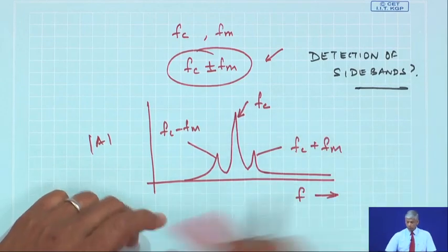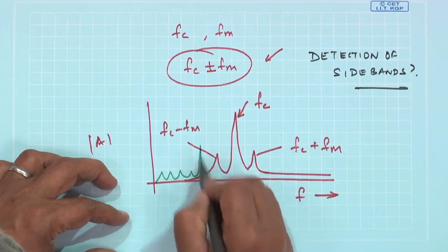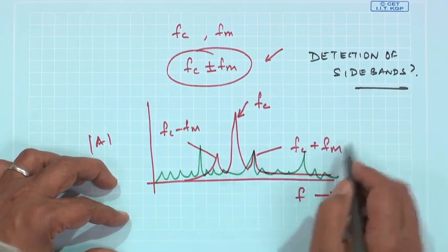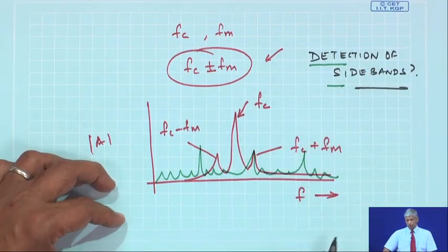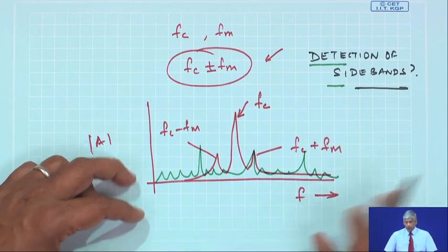Why? Because in a machinery signal where we are measuring from, say for example, a bearing location, there will be instances where there will be a lot of other frequencies in such signals. So, the detection becomes very difficult. So, this is another technique of detecting sidebands in a signal, and this is actually done through what is known as Cepstrum.